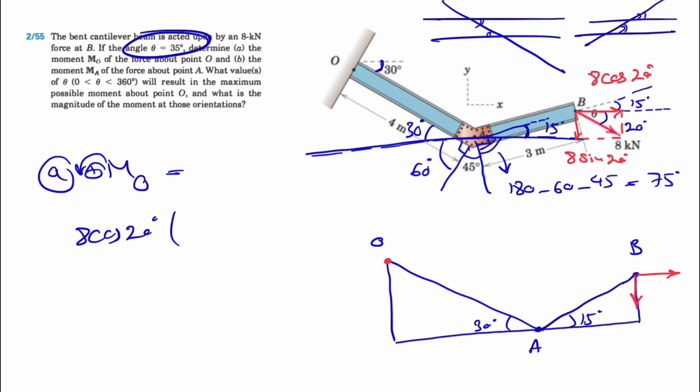So we are trying to find a moment about point O. As I mentioned, the moment of the x component, as we can see, is in this direction about point O, so counterclockwise positive. And the vertical distance that we are looking for is basically this. This is the line of action, and we are interested in this distance, which would be basically this side of the left triangle minus this side of the triangle on the right hand side.